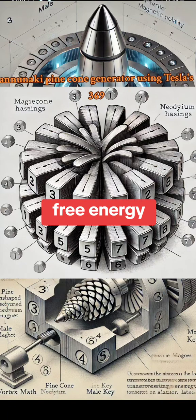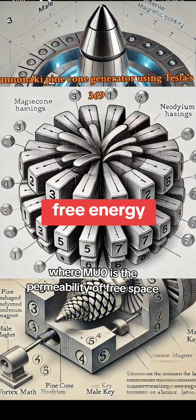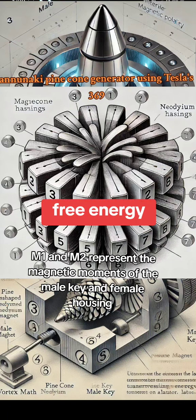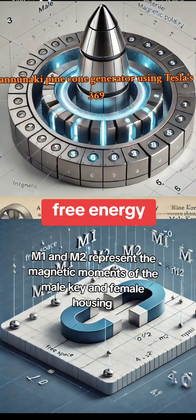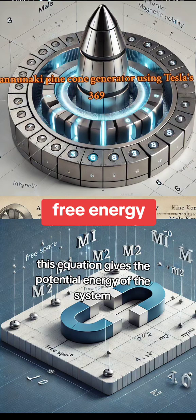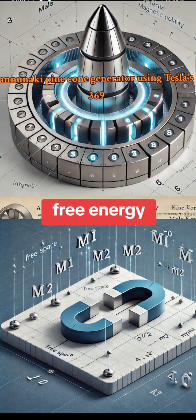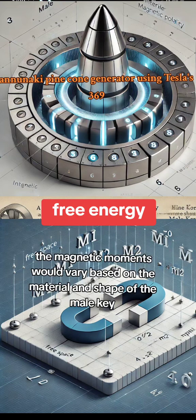Mathematical foundation. We can now revisit the mathematical equation you provided and apply it to the context of your generator. Equation for potential energy: U = -(1/2) μ0 · M1 · M2 / (4πR), where μ0 is the permeability of free space, M1 and M2 represent the magnetic moments of the male key and female housing, and R is the separation distance between the magnetic moments. This equation gives the potential energy of the system when the male key and female housing interact magnetically. In your setup, the magnetic moments would vary based on the material and shape of the male key and housing.